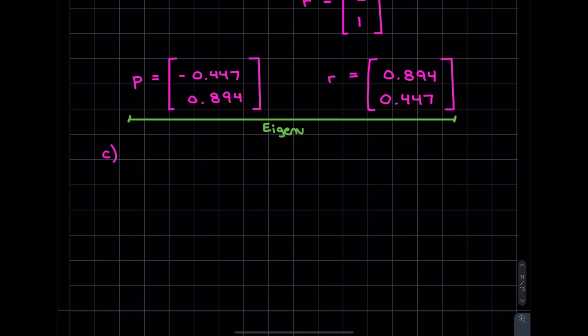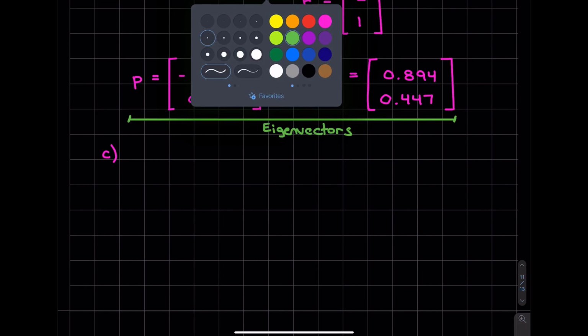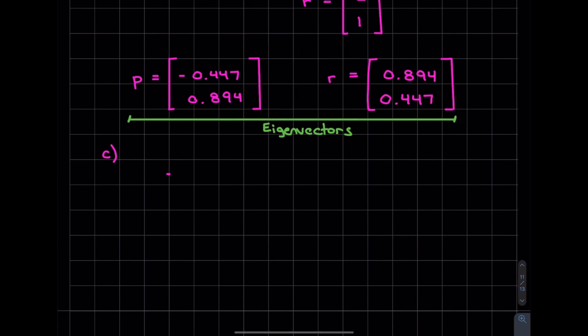These are eigenvectors. So we can say, okay, well, we remember what happens to symmetric matrices when they're transformed by eigenvectors. We remember that sigma prime is going to be equal to Q times sigma times Q transpose. Wait, this is just going to be a diagonal matrix. And the entries of this diagonal matrix will be the eigenvalues.